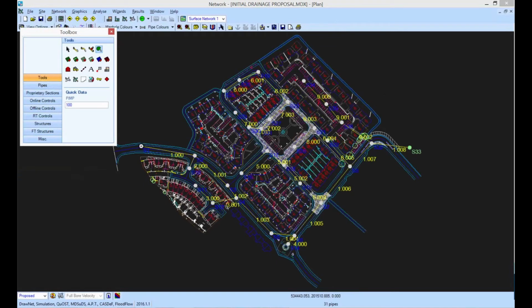So for this first manhole, manhole S1, the top of my run, I'm going to say there's going to be an area that's going to drain to this. It's got a percentage impermeability of 100, so it's going to be the complete impervious area. Just for demonstration purposes, I'm going to see what happens if I define a very large area to this pipe. So I've defined a complete area. It's gone into the pipe now.